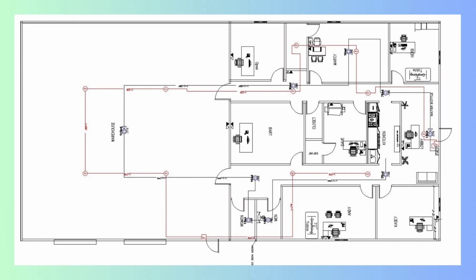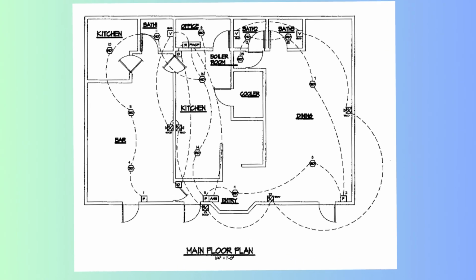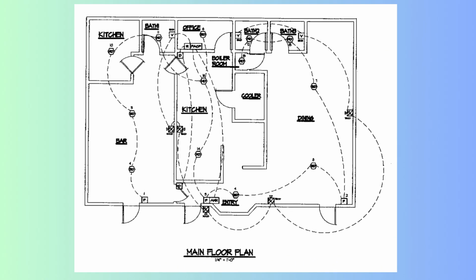Calculations: these determine the correct placement of detectors, the power supply needs, alarm signal strength, and evacuation time. Calculations ensure adequate coverage, battery backup, and system performance during an emergency. Together, design drawings and calculations ensure the fire alarm system meets building requirements and provides adequate protection for occupants.